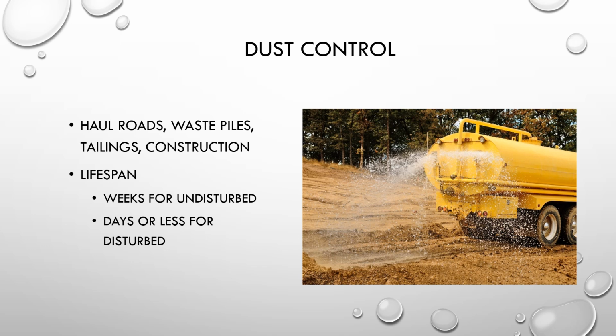A great example that comes to mind is, again, down at Disney World, there was a haul road that was leading to a landfill, and dust from this roadway was blowing onto a very high-end resort nearby. So there was a lot of complaints. It was covering cars. And so what we went in and did is a single application of the granular PAM. We mixed it into a water truck and applied it to the surface of this roadway.